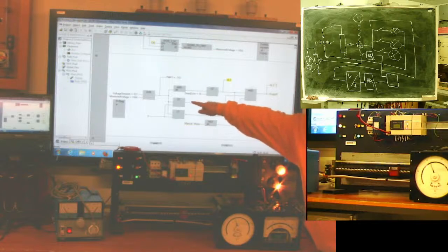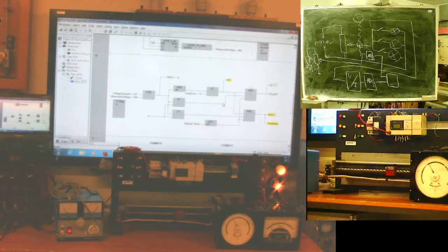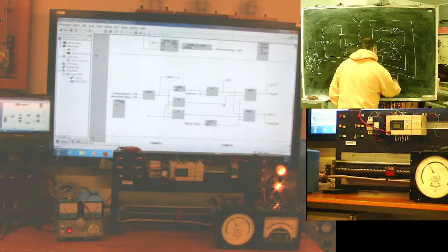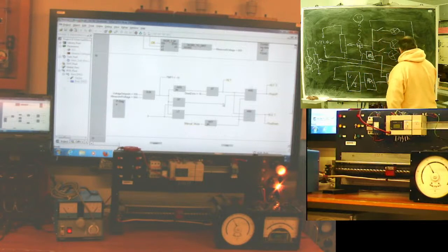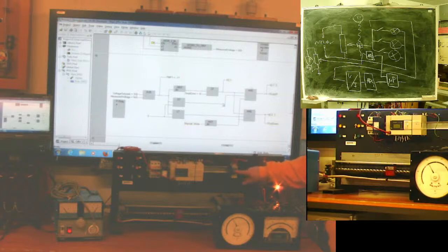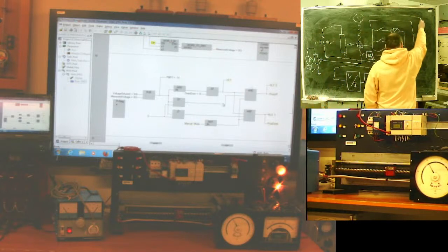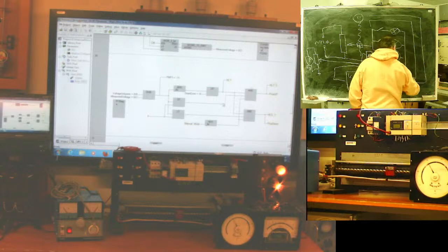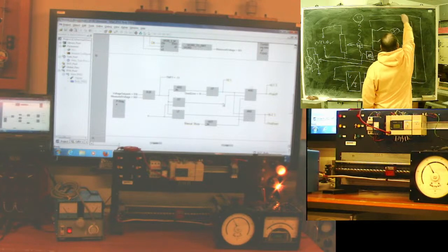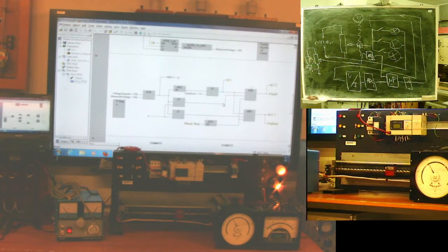You see, voltage set point, measured voltage. The microcontroller drives these 2 relays, up or down. Left, right. And up, down. And they are driving what? The motor, with my block of relays. Actually, what do we see? A closed loop system.